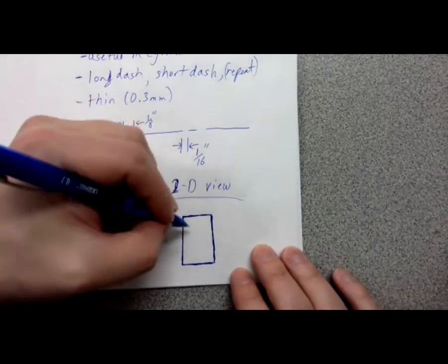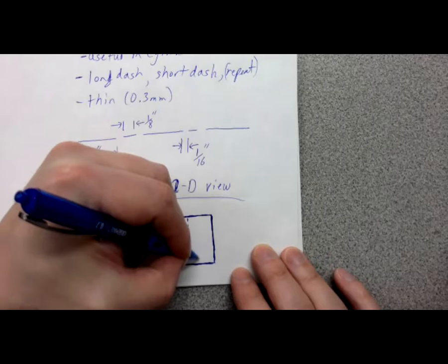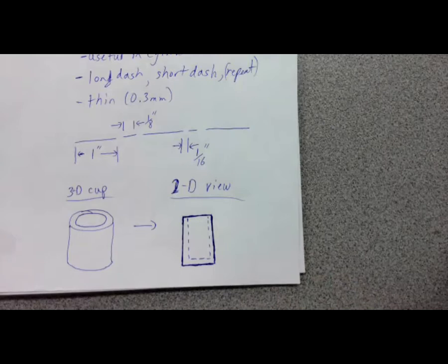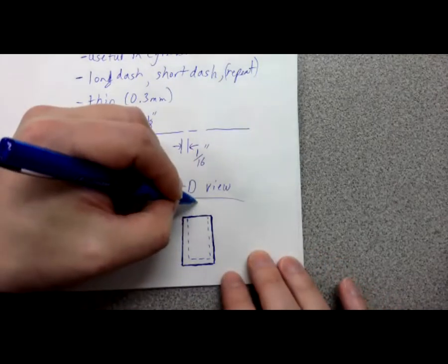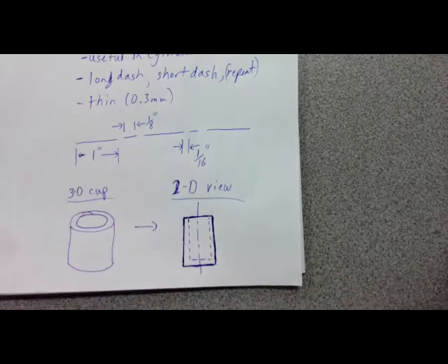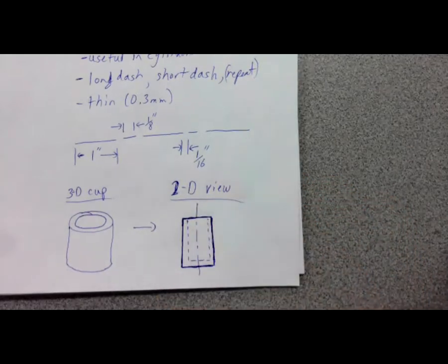And then I can go through and say, there is this internal cylinder removed that we can't see from the side, but I can communicate to the viewer, hey, there is something else going on here you can't see, and this is roughly its shape. And then I can also say it's symmetric, right down the middle of this thing. It was the same on both sides. If I need to tell somebody how to build something like this, I could communicate the height, the thickness on one side, and the radius. Because I've said it's symmetric, I would only have to define one side because the other side has to match because of this center line here.